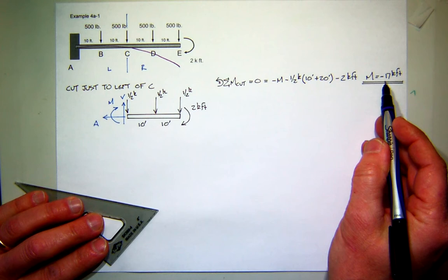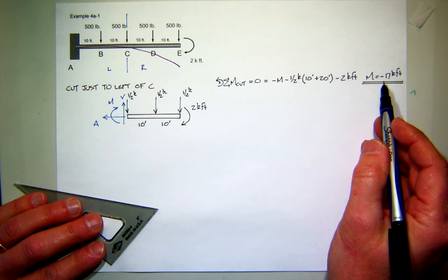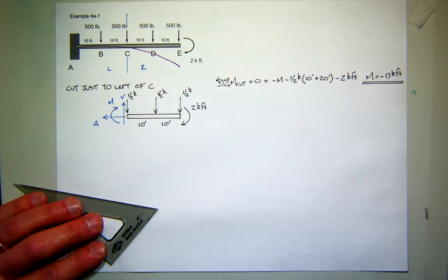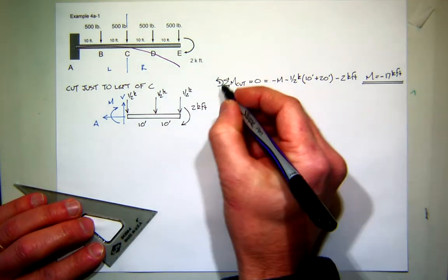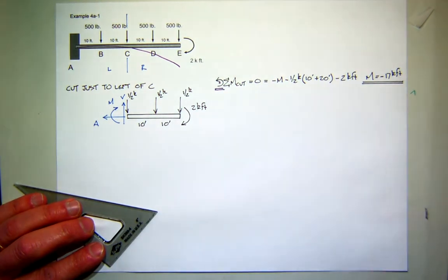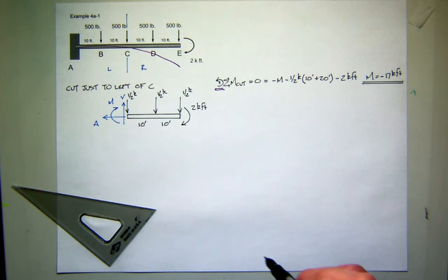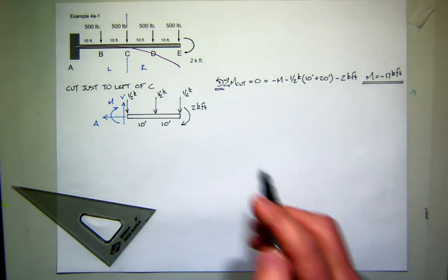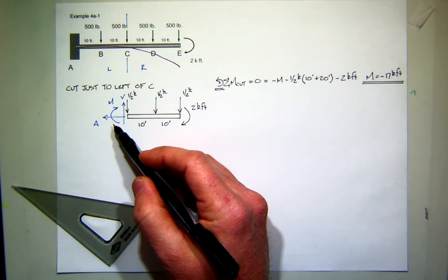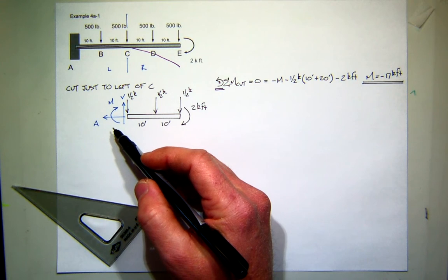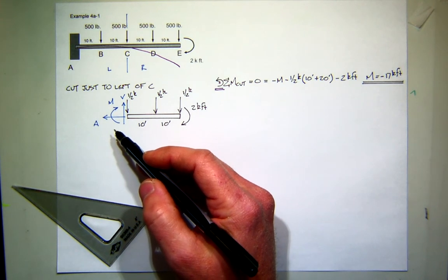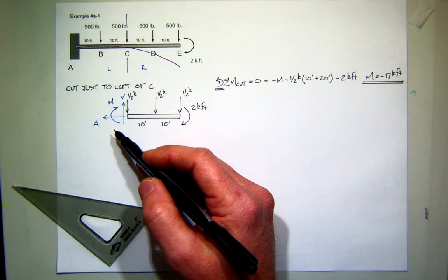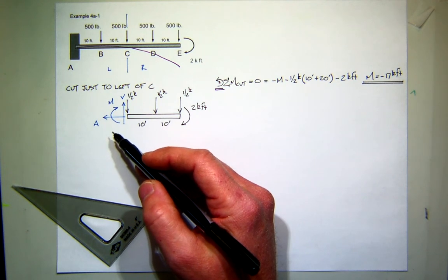Well, when you did statics, you always assumed counterclockwise for moment is positive. Right here, this is my static sign convention, right-hand rule. But that's just for accounting for the moments in statics. The resulting moment, now that we're calling it a bending moment, has a sign convention. And those will come into play when you communicate to another engineer and you say that beam has the largest moment, that beam is a negative moment, that means something. It's not arbitrary. And that's when your moment diagrams matter.